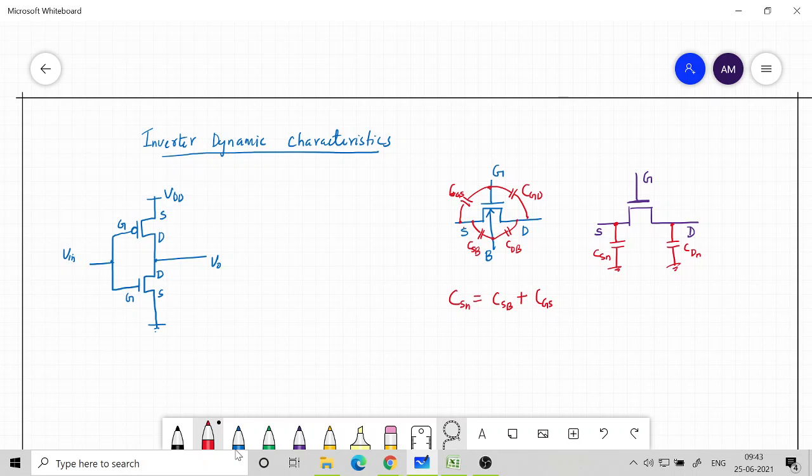Because the bulk and gate terminals will go to some power supply, either the signal supply or, for bulk, usually ground for NMOS. So for the AC equivalent model, we can consider all the capacitors connected to the source point as grounded like this, and similarly all the capacitors connected to the drain side. This is a simple model. We want to simplify the model as much as possible.